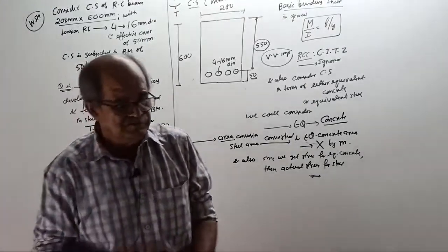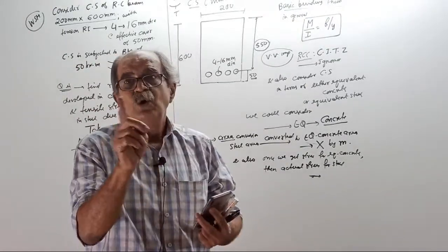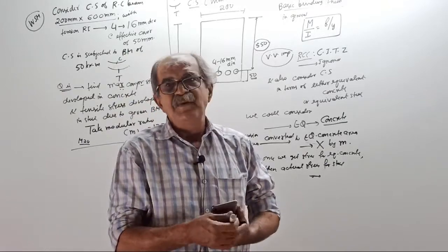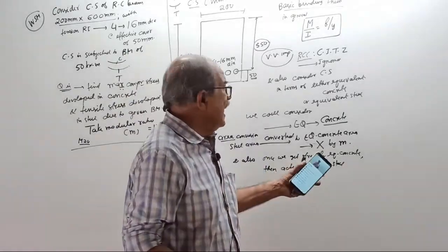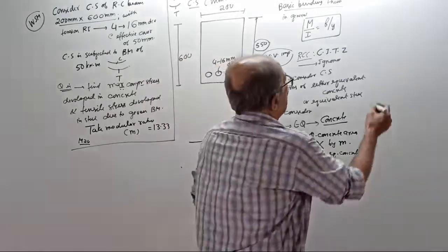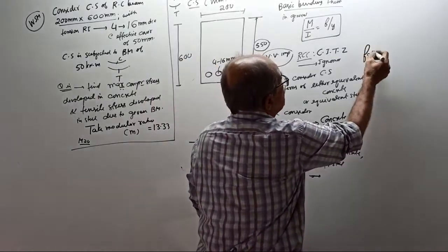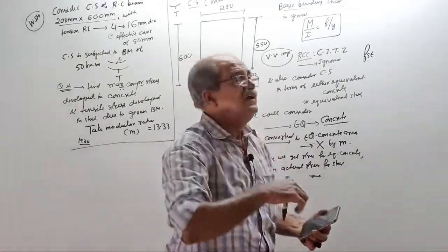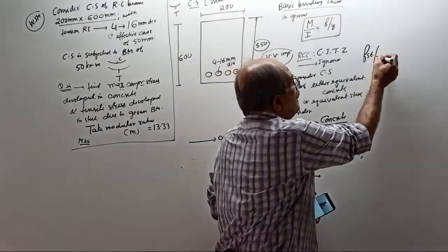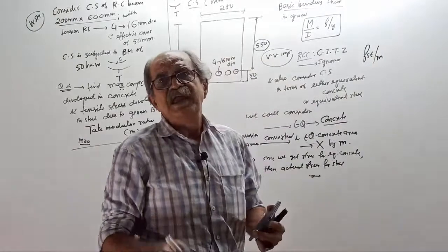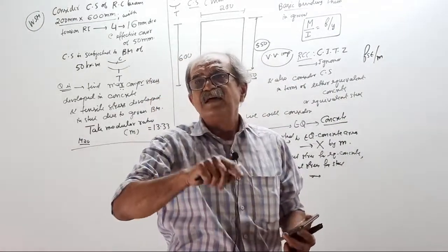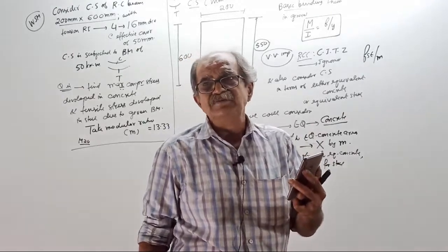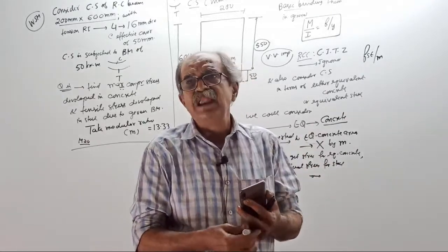Actual stress for... no, not divide. Be careful, I am trying to trap. In RCC what you do is, you write stress in steel, FST. I want to convert steel stress to concrete, then you divide by M. Here not that way. We get stress in concrete. Then to convert to steel, what do you have to do? Not divide. These are all called elementary doubts.